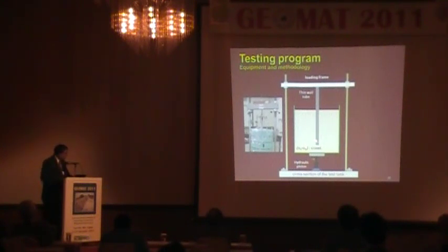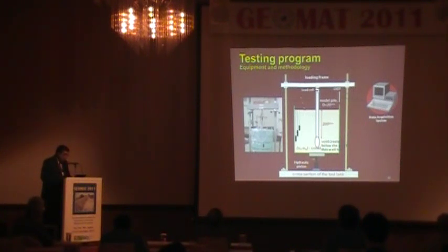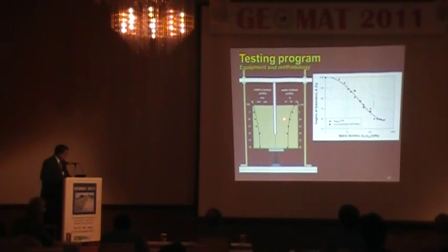And as compacted, when the matric suction is constant, we used a thin wall tube to take out a soil sample of 220 mm length, and then introduced a pile and made sure that a void was introduced. So now this pile is loaded into this void such that only friction is generated and there is no end bearing resistance. All the data has been collected. And again, the tensiometers were helpful in measuring the suction. The readings with respect to suction as well as water content were determined, and I have shown you some details of how those things have been done.